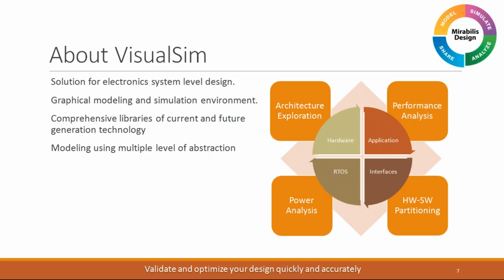and you configure them based on your requirements. And also the libraries that we provide help you to model the hardware architectural elements, application behavior sequences, defining an interface itself, or how exactly an RTOS is going to run. And with the help of these different sets of library blocks, you can conduct a variety of analyses, all the way from performance analysis, hardware software partitioning, and power analysis, and by looking at these different reports, you can select a particular architectural element itself.